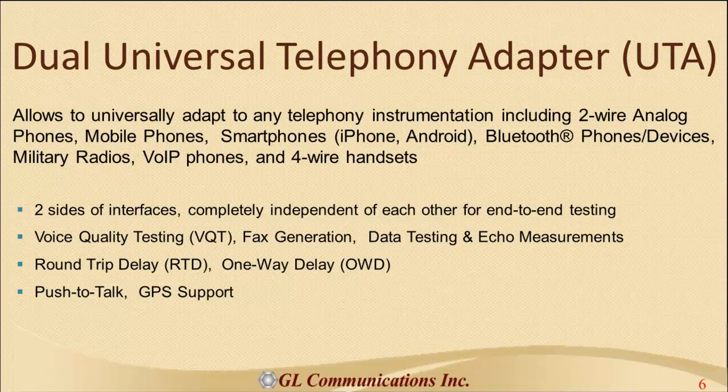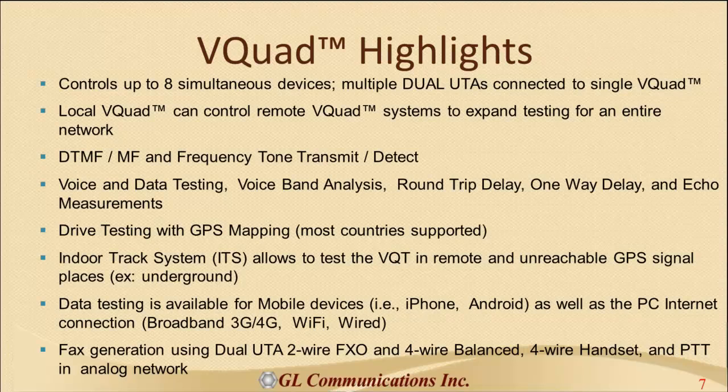We support voice quality testing, and we support fax generation, fax over 2-wire as well as 4-wire. All industry standard modems are currently supported, like V29 and V34. The latest V34 modem standard is supported. We support data testing and echo measurements. Like said earlier, we support RTD, one-way delay and round-trip delay, push-to-talk, and GPS support. These are some of the system highlights.